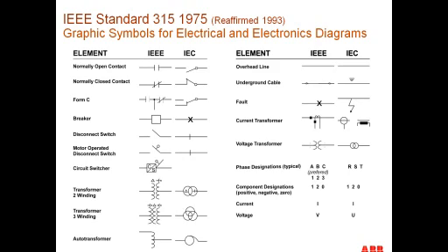In this country, lots of different customers use A, B, C. Some use 1, 2, 3. But most times in the IEC world, they use R, S, T for phase designation. We use the same for positive, negative, and zero sequence components, 1, 2, and 0 in both cases. And for voltage, in the IEC world they use U, and in the IEEE world, they use a V.